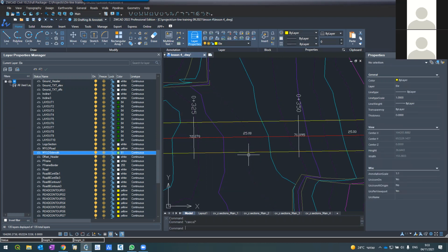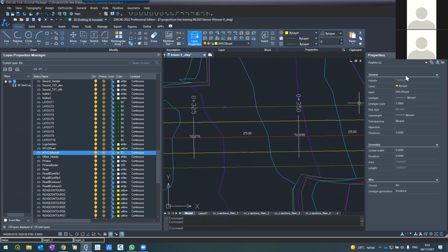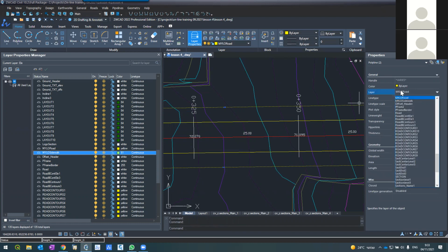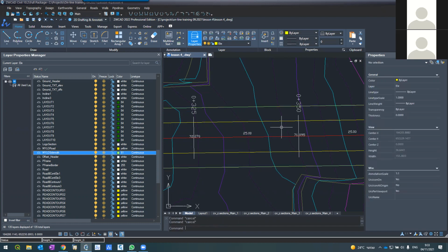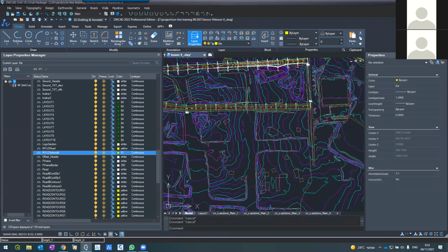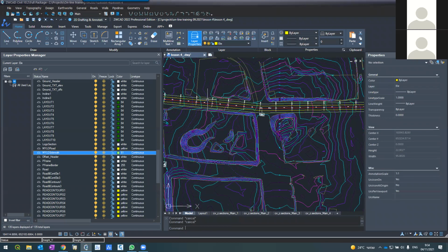And I'm doing the same, let's say a sidewalk of 3.5 meters to here, and the 2 shorter ones, also 3.5 meters, from here to here. Okay, good. And this one, I would change it to my layout sidewalk. Good. So this is what I designed. I just drew my road.